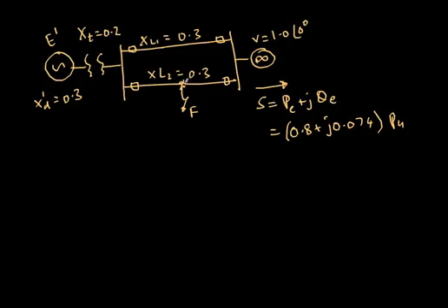When the fault is cleared, this circuit breaker and this circuit breaker are open circuited, so this entire line is isolated, and now the transmission network is only one single line, so we still have some power flow going on. The maximum power transfer limits in each of these cases, that is before the fault, during the fault, and after the fault, will be different. That's what we'll have to calculate.